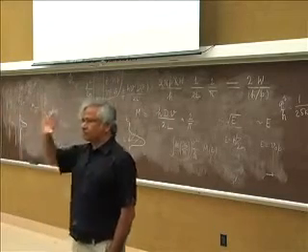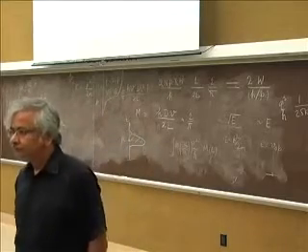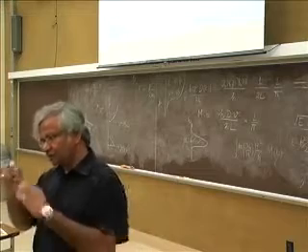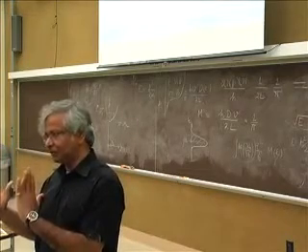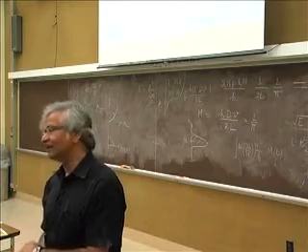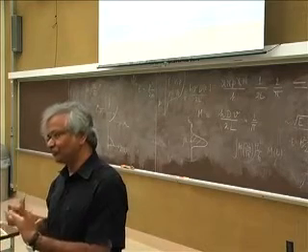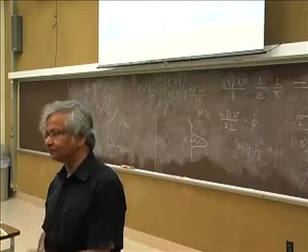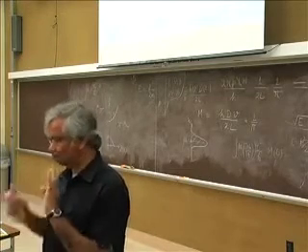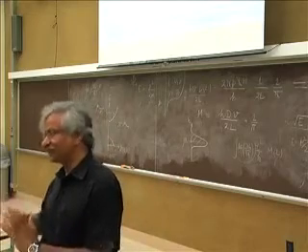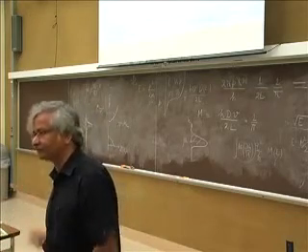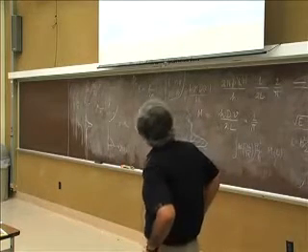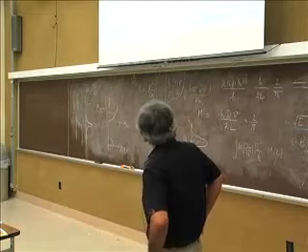Any other questions, please? The carbon nanotube example again. If you measure the resistance, it's going to be like 6 point something. So the smallest carbon nanotubes, ballistic, will give 6 kilo ohms. Well, because even the smallest one has these 4 levels, 4 channels in parallel, the 2 spins and the 2 valleys. You always go back to 25K. 25K is per channel, and then channels can come from spin, from valley, etc.